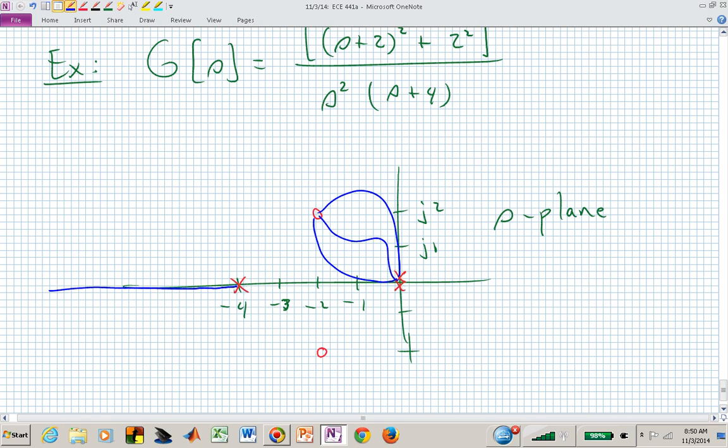We could also talk about the angle of departure at the origin. That's what Rule 6 will allow us to do. So we'll pick up at that point. We're going to compute the angle close to that zero upstairs, and the net angle needs to be minus 180. We'll use that to figure out how we're approaching that zero.